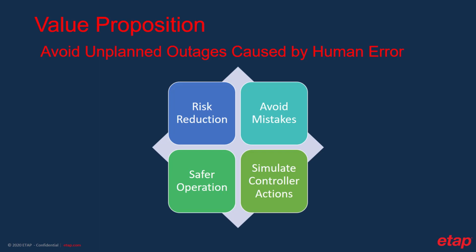The eOTS challenges operators to learn about and gain knowledge of the behavior of the power system and associated processes before facing real-world situations. It helps to avoid mistakes from wrong switching actions by supporting approved switching sequences of operations to guide operators, where operators can follow tested and approved switching orders for various contingencies, normal operations, as well as emergency and abnormal conditions through virtual simulation.